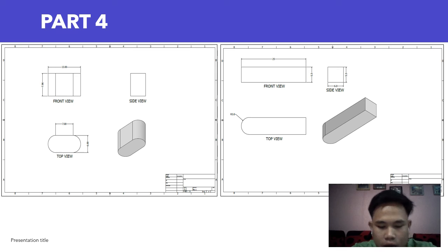For the left side, you open the part and begin with a length of 40mm and a height of 8mm. Then I will do a fillet on the corner with a radius of 4mm. I will extrude it to the dimension, where the width will be 7mm.